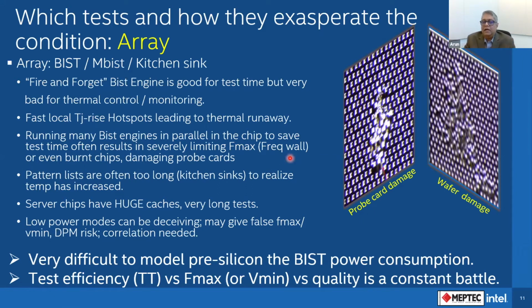the chip. This is not only at packaged final test, even at wafer test you can see the wafer damage here, right? It just burns up all the probes. And one of my managers used to say, "Oh, you burnt up a wafer, okay, bad Arun, but it is one wafer, it's okay." I go and tell him, "No, it's not only the wafer, I burnt the probe card also." And if a probe card goes away, then it's easily $50 to $100,000, and not only that, a downtime for the line. So it is a very bad test. So array tests are notorious for burning the wafers here.